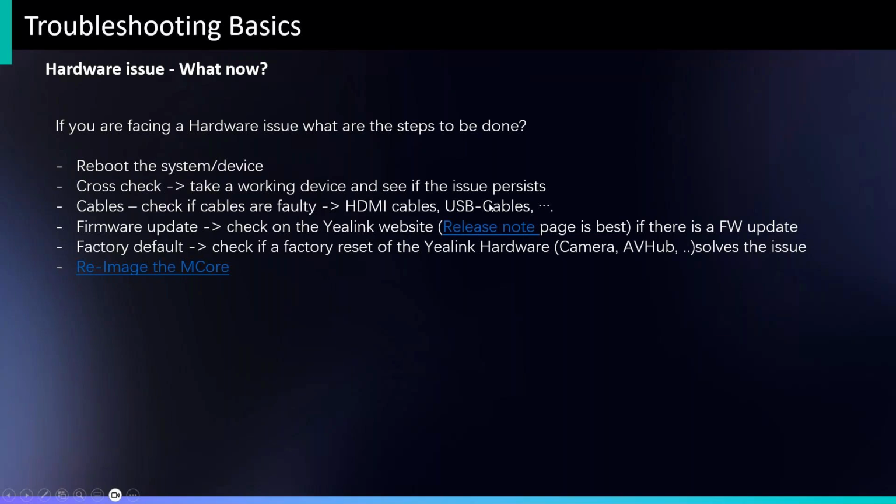Is the switch where the devices are connected having a faulty port? Does it have EEE, the energy efficient Ethernet, enabled? Because all these devices are using PoE+, Yealink is asking for switches that have no EEE enabled or where it can be turned off.